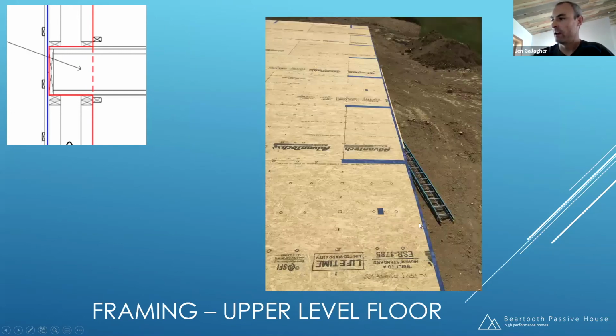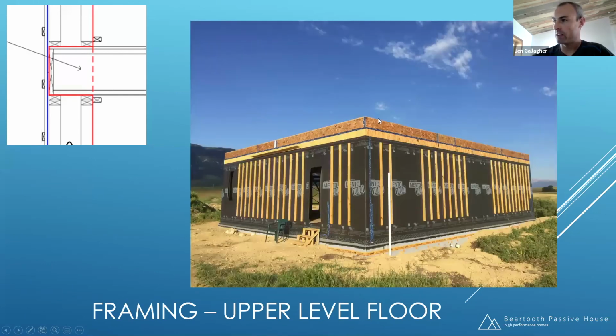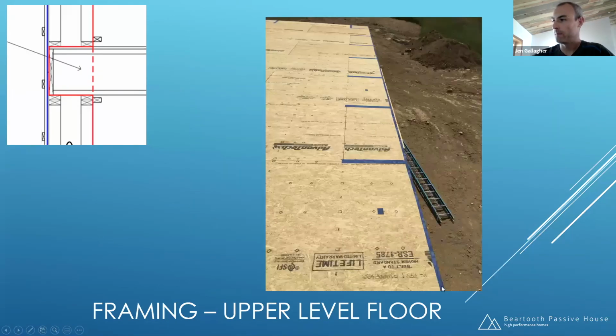And then I'm standing on top of that second floor system. And now that subfloor is taped to the top of this rim board. In this picture, that tape isn't in place. And then every single one of my seams is taped 18 inches, 2 foot in or so, because I'm going to be setting my second floor wall on here, and I have to connect this to the interior of my second floor wall.